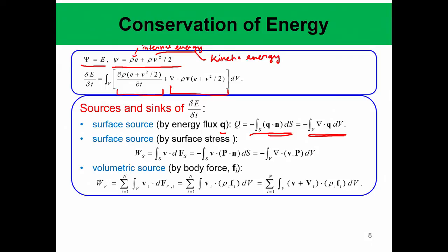And then there can also be surface stresses, which, if you remember, is flow work, that is the work done due to pushing the fluid because of external surface forces like pressure. To account for that, it will come into this form. And also there can be volumetric sources or body forces, which can do some work.